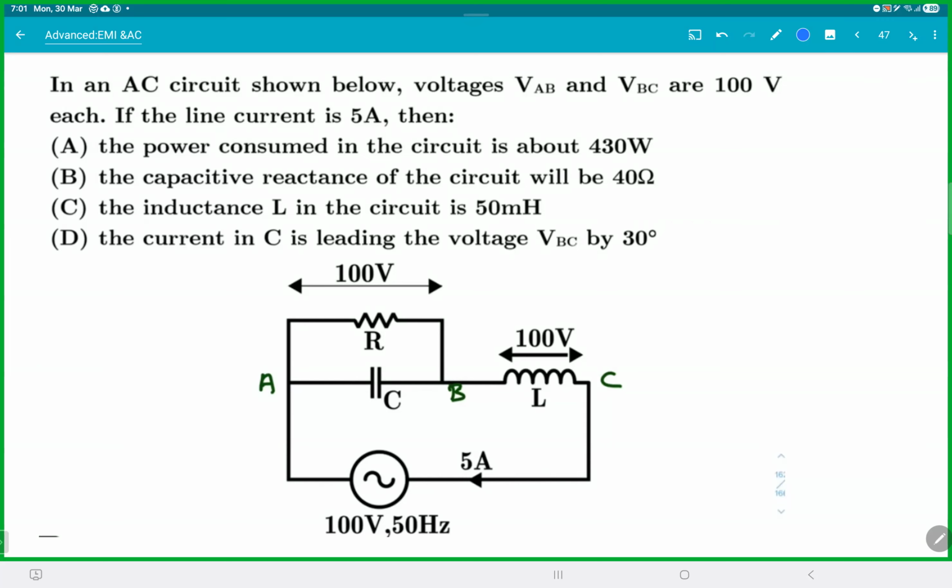Got something. Let's see. Got something. Yeah. 5 ampere. What do you think it is? If it is not, like they didn't give enough, 5 naught sine omega t. Like I keep saying, you see a constant number, always it is an RMS value.